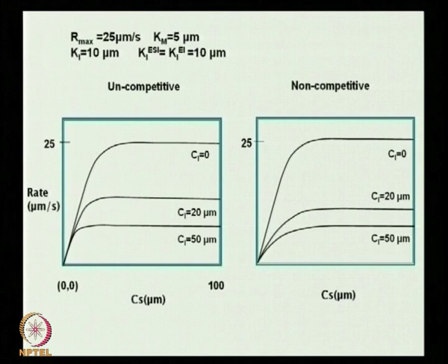So, what would be the other mechanisms? One of the ways, of course, is to keep the volume same, but increase the input output rates, right, for a steady state CSTR, so that the residence time is decreased. That is one of the possibilities, but what could be other possibilities? We can reduce the rate of formation of product. Then how will you reduce that? By varying the flow rates. No, flow rate we already said, that is a possibility, that you can increase the flow rate, as a result of which you can decrease the residence time. That is one possibility. What are other possibilities?